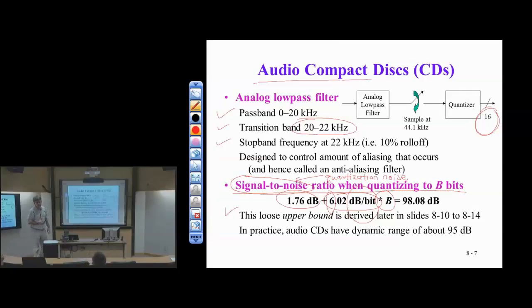What about QAM? In QAM there are actually 2 channels. So it works out to be 3 dB per bit, and that was in homework 6, last problem. 3 dB per bit, 2 channels. That's why it's less. And the offset in QAM, in the problem you had, was 4 dB in homework 6. So 3 dB per bit for QAM. Another reason why QAM is a big win over PAM. So if I have 50 dB in my channel, I can either do 8 bits of PAM or I can do 16 bits of QAM. So it's a big difference.